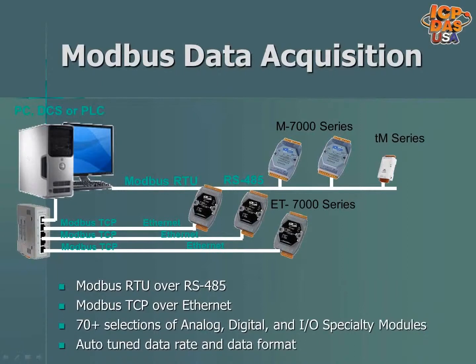Modbus RTU-based equipment communicates over RS-485, which communicates over 2 copper wires that are usually twisted around each other. They call it twisted pair. Modbus RTU supports communication distances up to 1,200 meters or 4,000 feet without a repeater. There are different speeds at which Modbus RTU devices can communicate, like between 1200 to 115,200 bits per second.